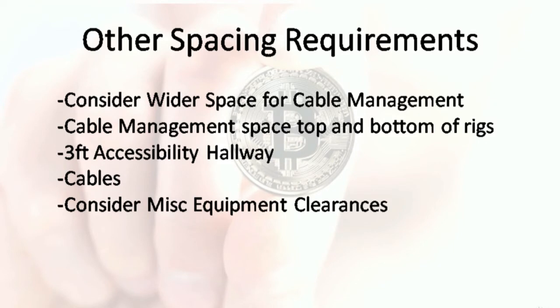Outside from that, the cable is another important factor when looking at the space that you need. We will look at cabling in another video of this course. Lastly, you may have backup generators, switches, as well as other items such as electrical panels, etc. And most of these will require specific clearances as well as other miscellaneous requirements. These requirements will differ depending on where you are located, so please check your local electric code for further details.